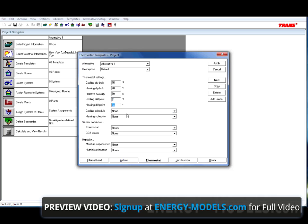When a drift point is entered, the room will be allowed to drift from the set point to the drift point when the people schedule drops to 5%. When the people schedule is above 5%, the room is then conditioned to the room set point. The sensor locations are also enabled, but are typically left unaltered, and they will not be addressed in this lesson.